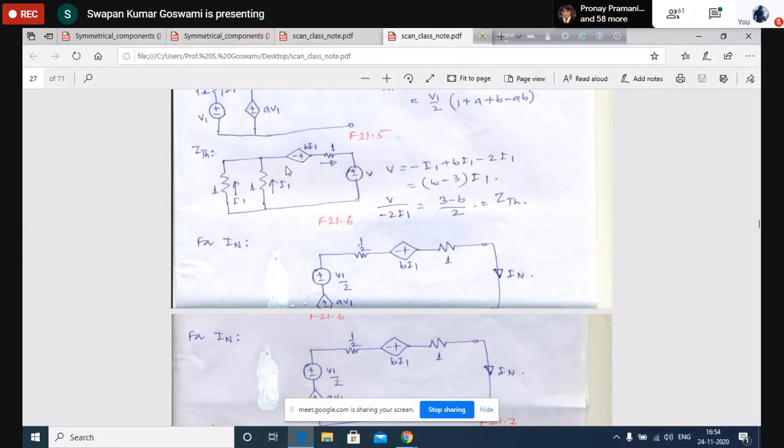So first of all, some current must flow through this branch. To make this current flow through this branch, we have to connect a source here, and that source is say V. So I determine V, I determine the current delivered by this source, then V by I will be the Thevenin impedance. Okay. Now once you do this, you calculate the voltage.